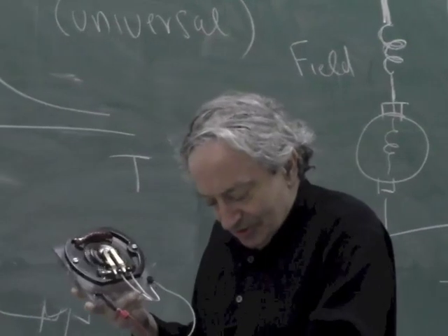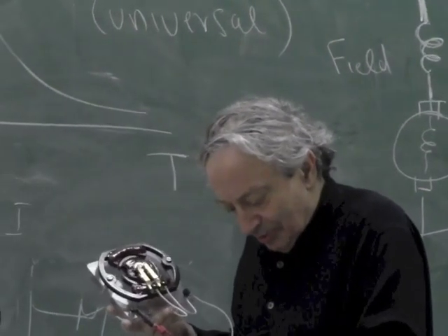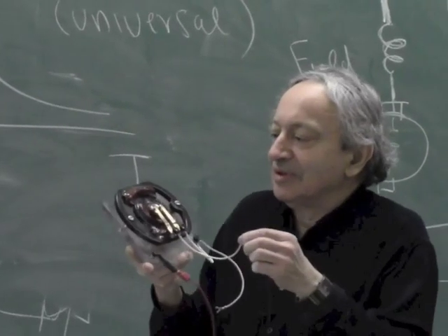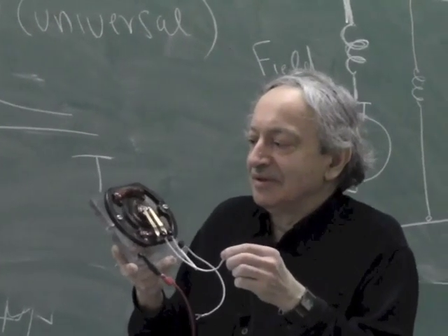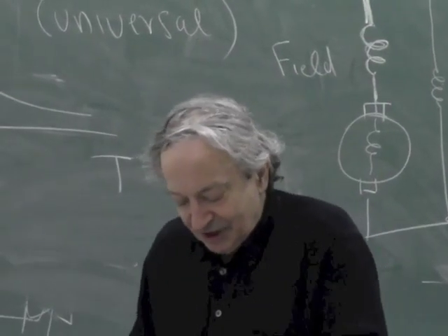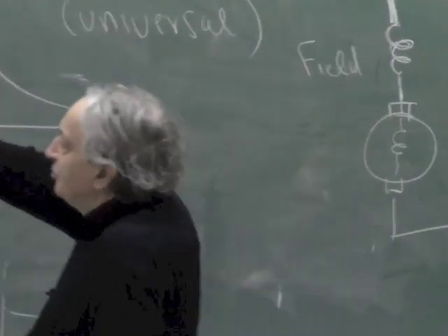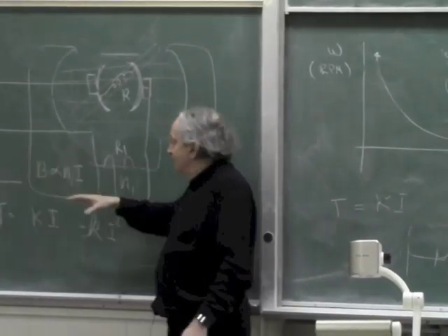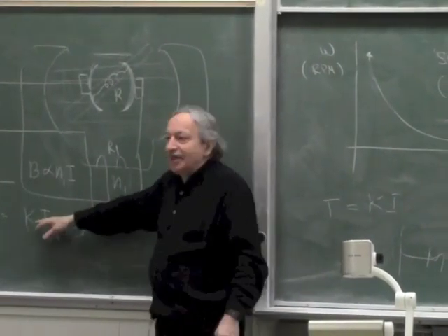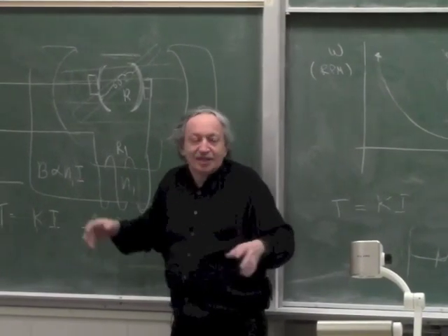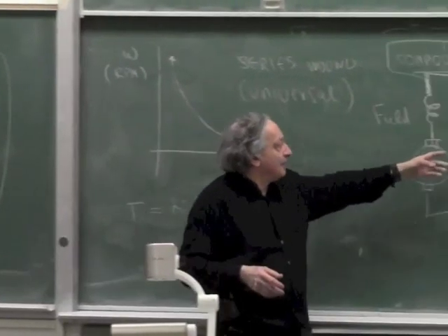Maybe let's do it at a lower speed, maybe it will be more evident. But if you take a power tool, no, it's limited by friction. Remember, any friction, not just air friction, in this motor will require a minimum current, and a minimum current will determine some minimum K. And the moment there's a minimum K, it's like a shunt wound or compound wound.